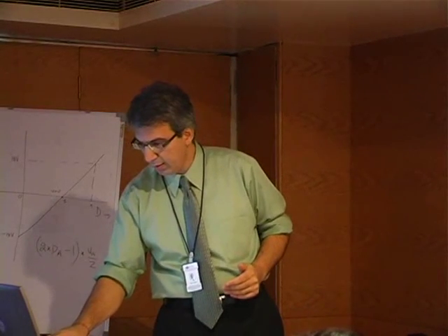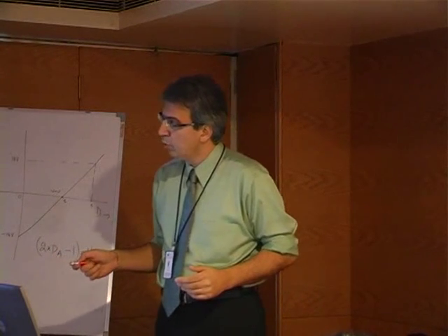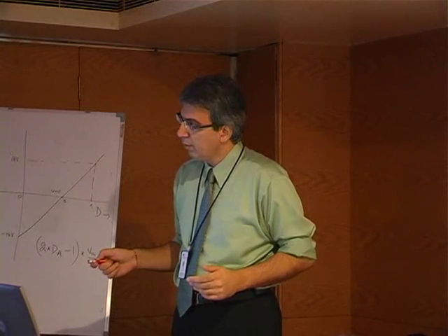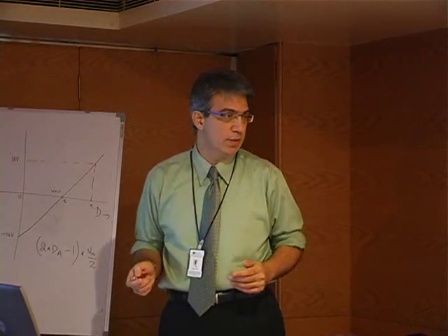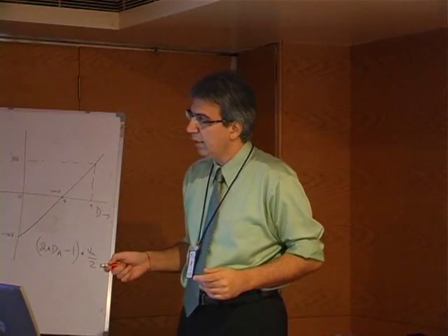So here I think I can show you how it works. When I have an amplitude modulation, let's say I set it at 2.5, then my duty cycle command stays at 1 for a longer period of time. So this is what you do in overmodulation. The theory in overmodulation